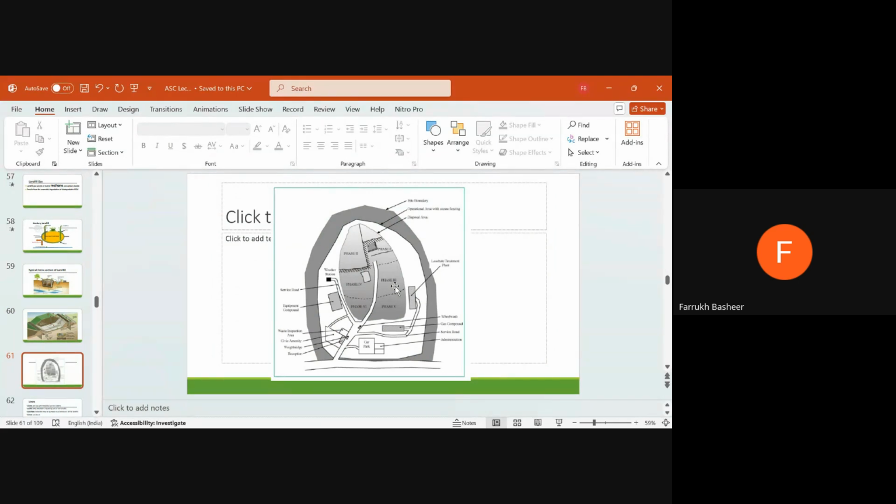This is a typical plan of a landfill area. You are not going to dump your solid waste in a continuous manner. You have to manage it properly. For example, in a whole area you have to dump solid waste in phase 1, then you will go for phase 2, phase 3, phase 4, phase 5, phase 6. So in that case, each cell of a landfill will be completed first, covered, and finally we will move towards the second phase, third phase. So proper management of solid waste will be done.